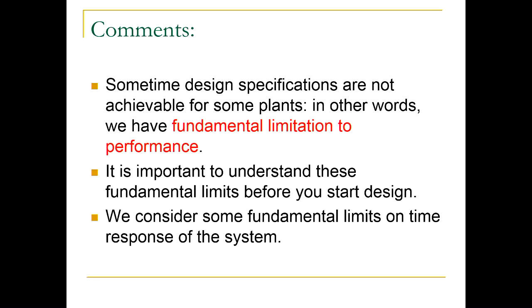If you remember, unstable zeros and undershoot, when I was talking about it, I was giving you an example of a motorcycle. When there are races and they want to turn right, they go far to the left. And the faster they go, the further to the left they need to go in order to turn right. That's basically an example of undershoot.